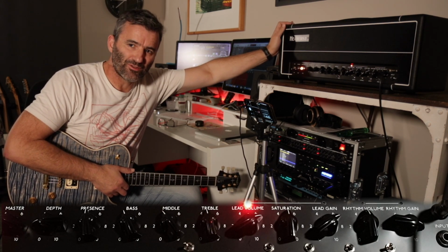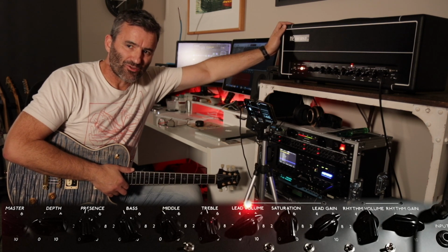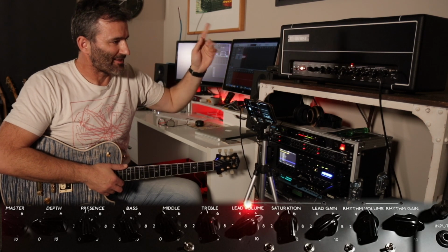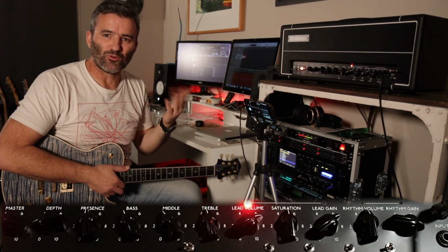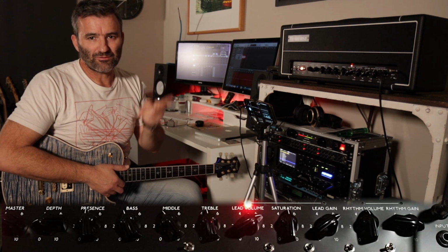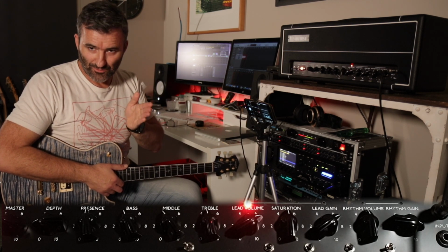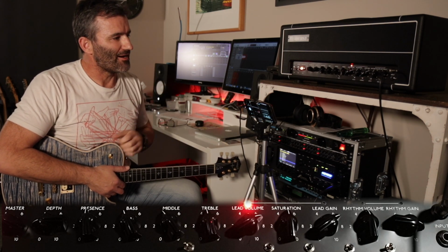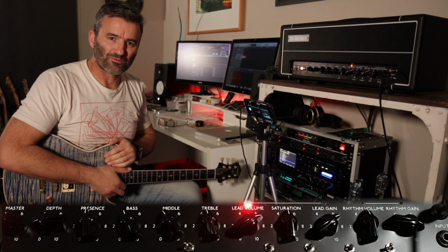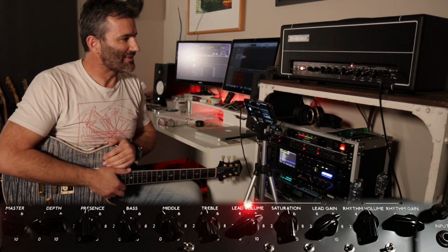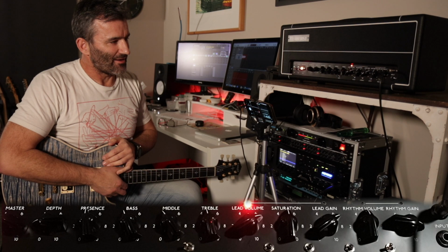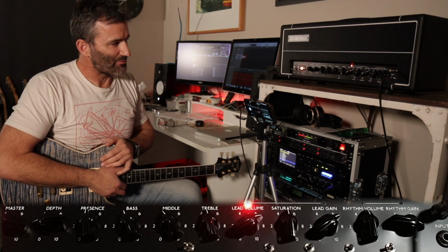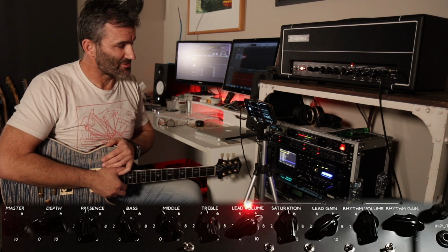I want to use this video to demonstrate how you can use MIDI switching to integrate into one of your amps, particularly an amp like this that has basically 4 modes. You've got a rhythm channel with no boost, a rhythm channel with boost, a lead channel, and a lead channel with boost. So there's 4 modes. Now, you can control this with a conventional foot switch, of course, but with MIDI, you've got the ability to define these settings and have them recalled using program change messages or control change messages for that matter.